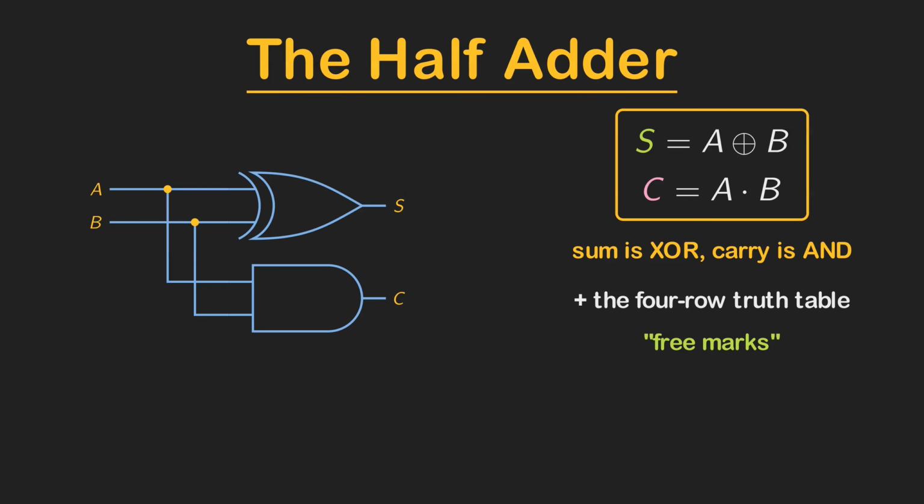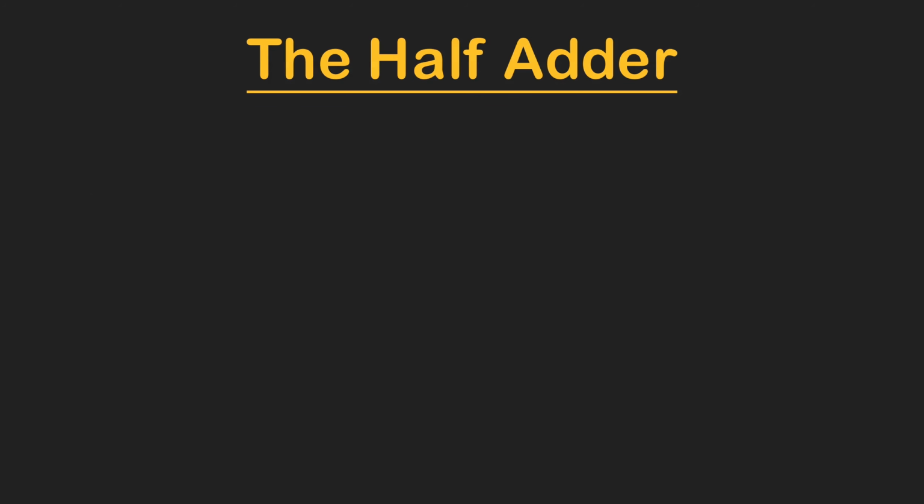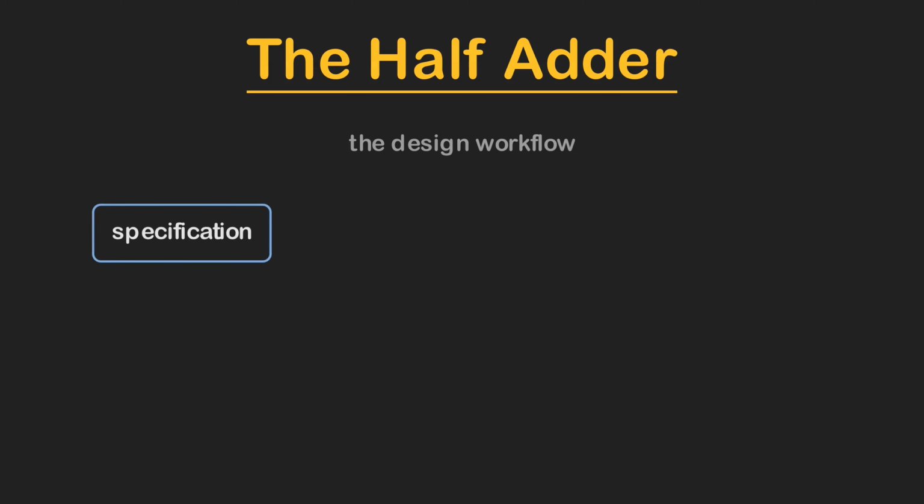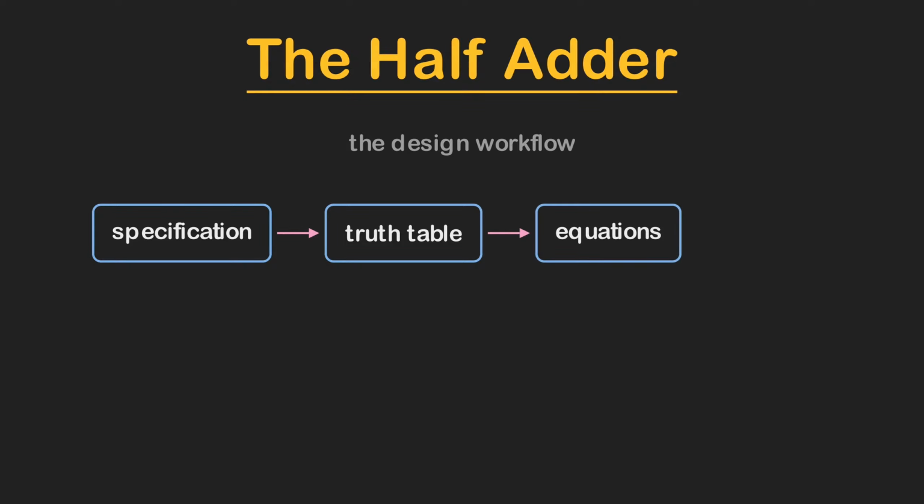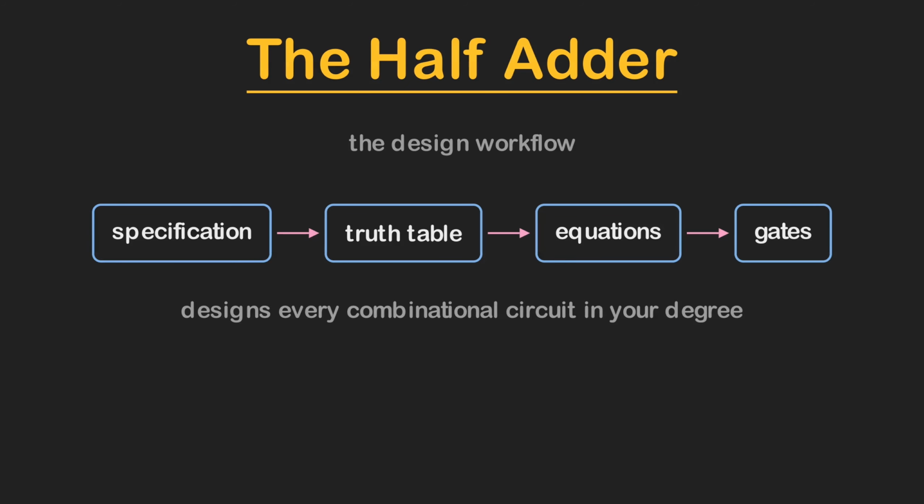Free marks in step 1 of every larger adder problem. One more thing, because it generalizes far beyond today. Notice the workflow we just used. When any exam asks you to design a small combinational circuit, immediately think specification, then truth table, then equations, then gates. That pipeline designs every combinational circuit in your degree.